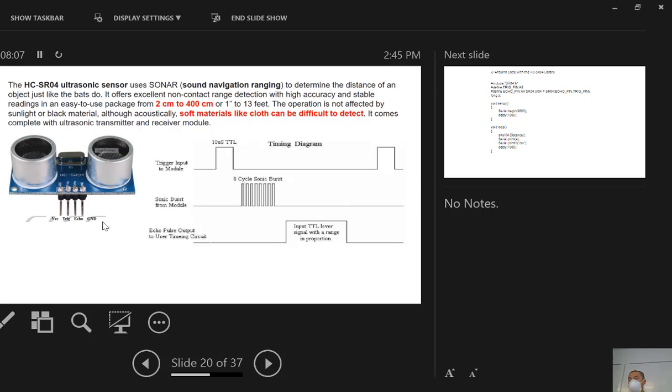You use an Arduino pin to send a 5 volt pulse with a duration of, for example, 10 microseconds. It's pretty easy to do, right? Just do a digital write to that trigger pin. And then the sonic burst from the module will be sent from the transmitter. You cannot use an oscilloscope to detect those pulses, right? Because they are just sound.